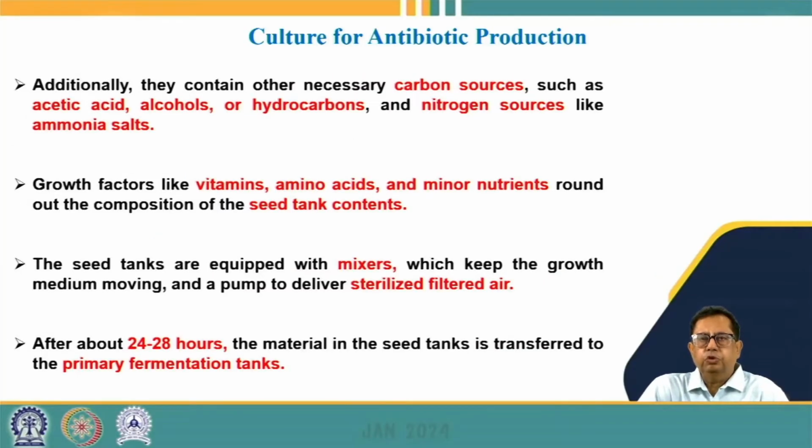And we also have to add carbon sources. For example, we can add acetic acid, alcohols, or hydrocarbons, so that the necessary carbon sources are available to the bacteria. And similarly, nitrogen sources also have to be added. For example, ammonia salts can be added here, so that they can get a high amount of nitrogen for their growth.